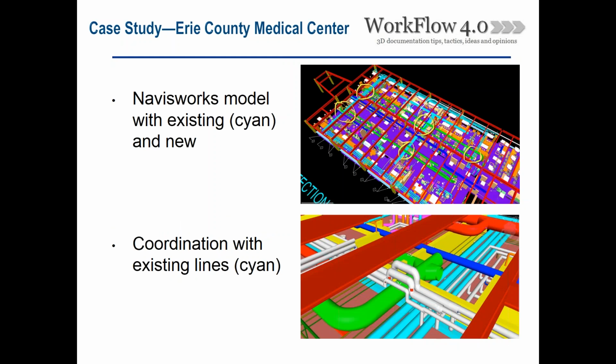Something else that came up from the pre-board scans that I'll talk about, the cleanouts. As they were building and drywalling, I got a call asking to locate some cleanouts and wasn't quite sure what they were looking for. Here the drywaller had closed up the walls and they were missing some cleanouts. Rather than ripping all the drywall out, we were able to take the pre-board scans, verify where those cleanouts were, and measure off of column lines so that they could poke the holes in the walls where they needed to be, especially since one of them was actually tiled over. So that saved them a lot of extra rework by identifying how those cleanouts were.